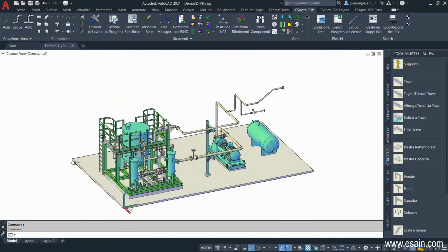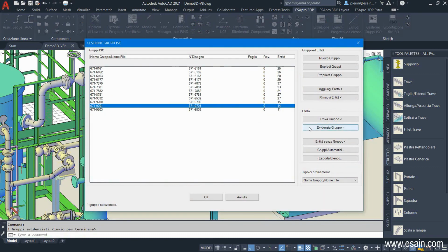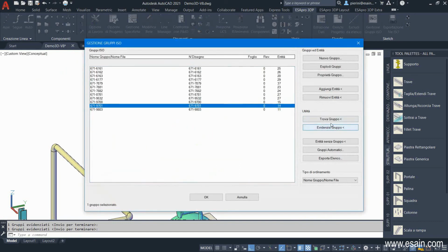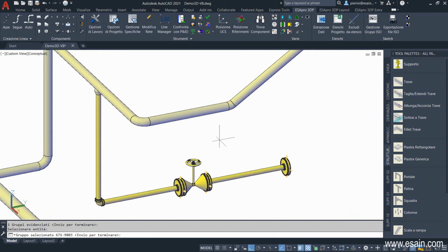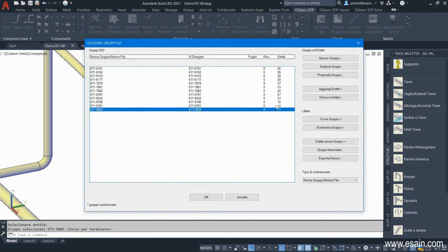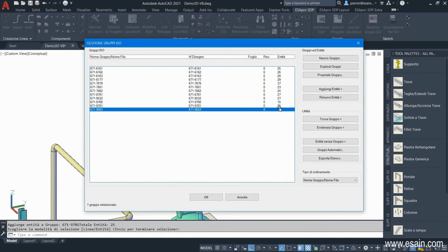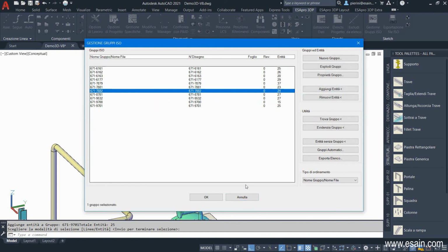Here we are highlighting the sketch number 9700. And here we highlight another sketch. In this case, this pipeline would be on one sheet and this branch on another sheet. But we can also choose to merge the two sheets. So if we select the first sheet, we may then decide to add this line to it. In this way, we can rearrange the sheets as we find most useful. We spared a page so the empty sheet could be deleted.